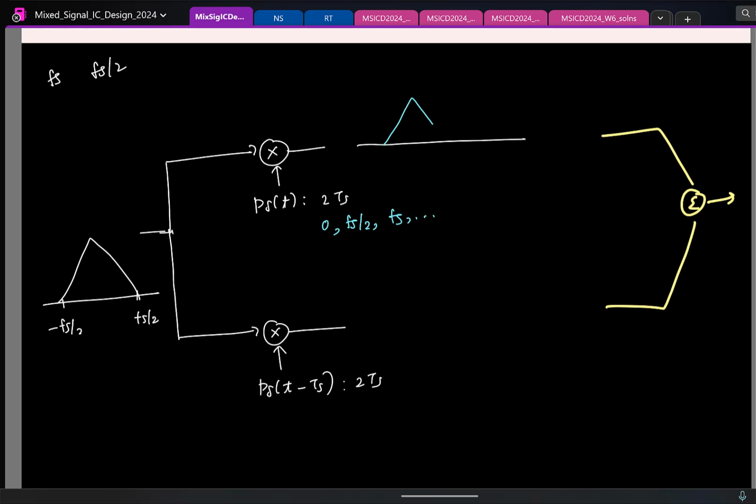So let's say that comes directly like this, minus fs by 2, plus fs by 2, this is 0. I have this getting convolved with an impulse around fs by 2. That will get shifted around fs by 2. So I'll draw it like this. And as you see, there is clearly aliasing happening. And when I convolve with fs, this is basically fs now. Fine. And this will keep doing this. And as you see, there is aliasing for sure.